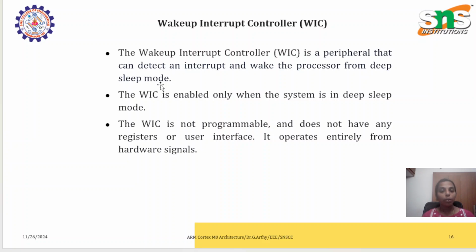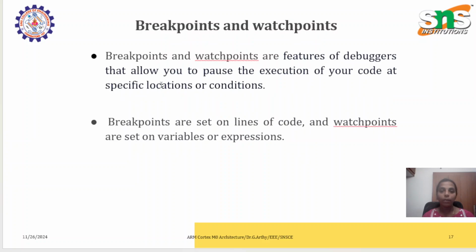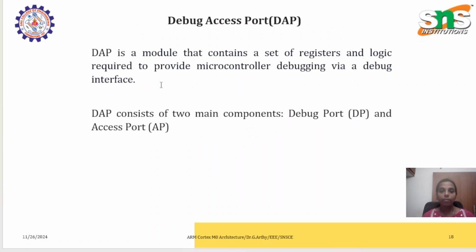It is not programmable and does not have any registers or user interface. It operates entirely based on hardware signals. Then we had breakpoints and watchpoints in the debug units. These are features of debuggers that allow us to pause the execution of the code at specific locations or conditions to check or to debug. Breakpoints are set on lines of code, and watchpoints are set on variables or expressions.